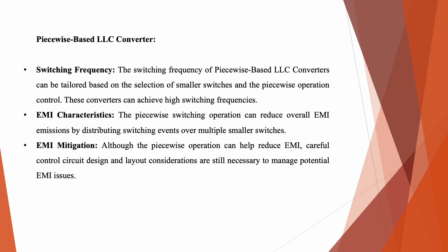The piecewise based LLC frequency and EMI. The switching frequency of the piecewise based LLC converter can be tailored based on the selection of the smaller switches and the piecewise operation control. These converters can achieve high switching frequencies. As for EMI characteristics, the piecewise switching operation can reduce overall EMI emissions by distributing switching events over multiple smaller switches. Although the piecewise operation can help reduce EMI, careful control design and layout consideration are still necessary to manage potential EMI issues.